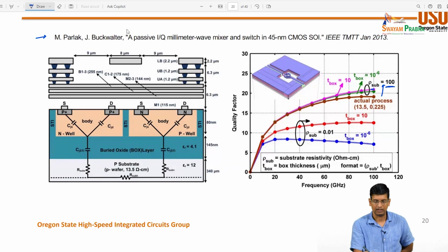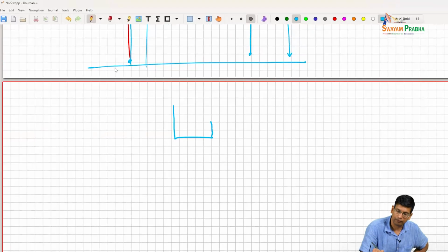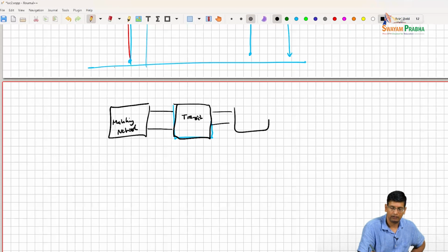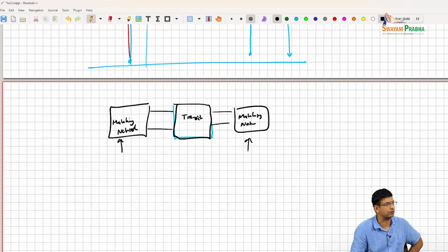So this basically is the sort of design that we just discussed, right? You see here that they have the inductor, they have the ground plane around it, and what is feeding the inductor and what is coming out of the inductor, that's like a transmission line. If you have the transistor single-ended, right, you are designing this matching network. So no differential. That is clear that it does nothing, right? It doesn't matter what component you use inside this network.